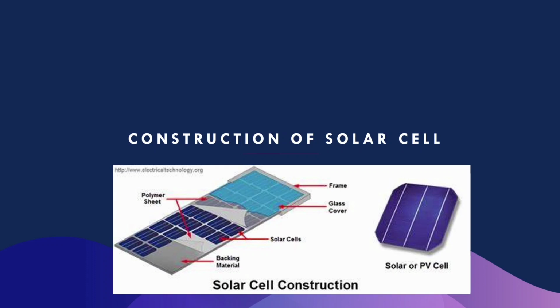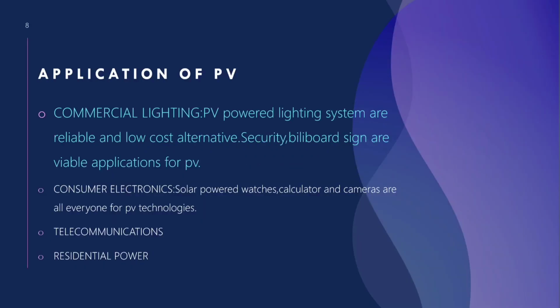N-type semiconductors have a larger electron concentration than hole concentration. The phrase N-type comes from the negative charge of the electron. In N-type semiconductors, electrons are the majority carriers and the holes are the minority carriers. A common dopant for N-type silicon is phosphorus.